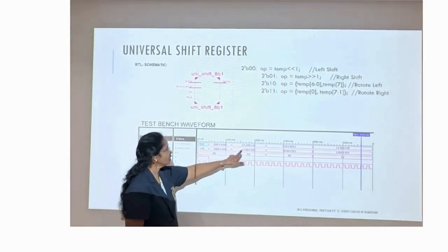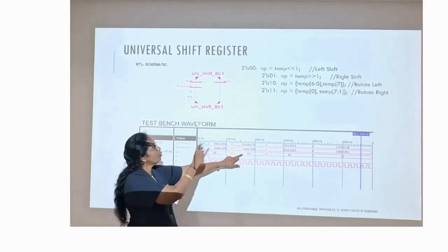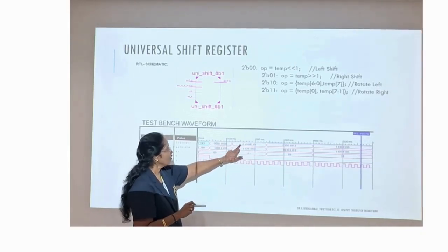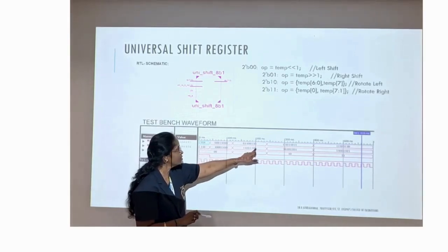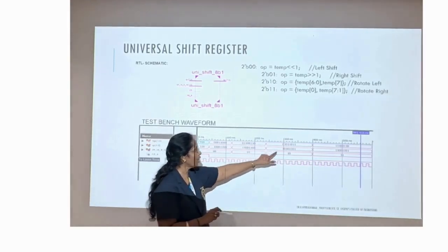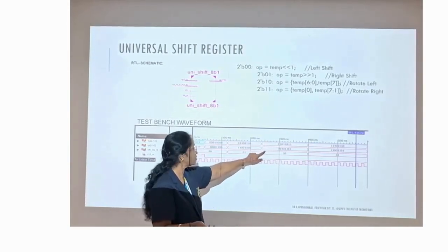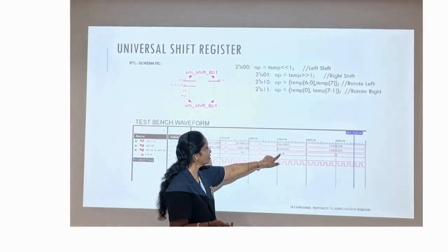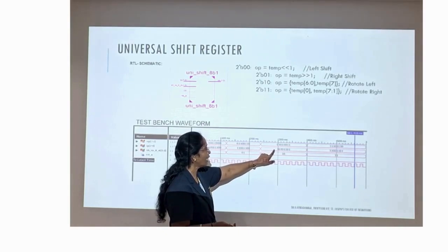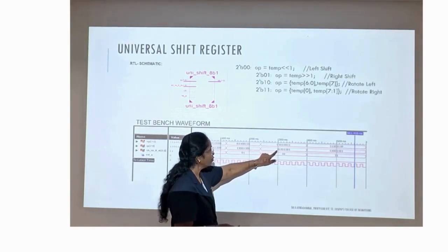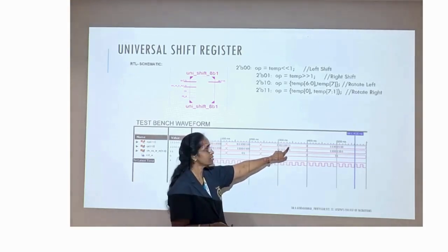When we set the input like this with 0, 1, that means shift right. Therefore, 0 is entered, and this 0 is moved there. Then when it is 1, 0, we gave the input like this in this IDE platform, because here 1, 0 is rotate left. Rotate left means all the values will be moved and the MSB bit is wrapped around and comes here. Therefore, you have this double one.